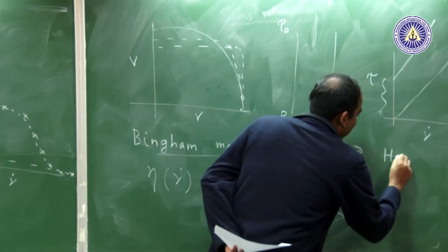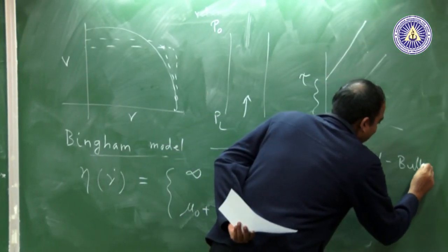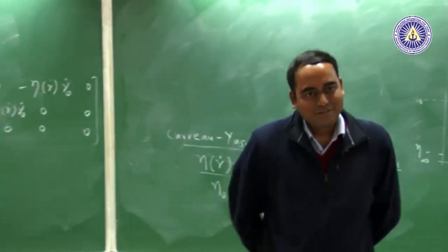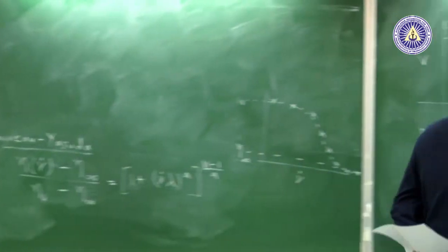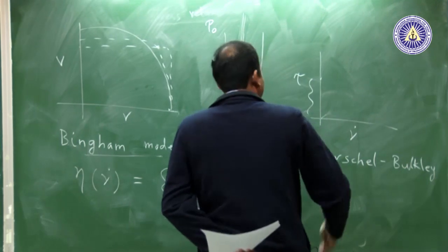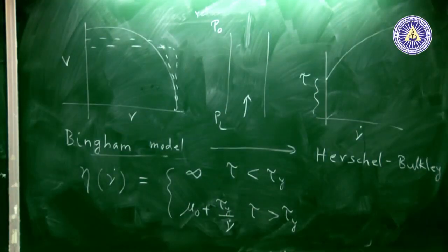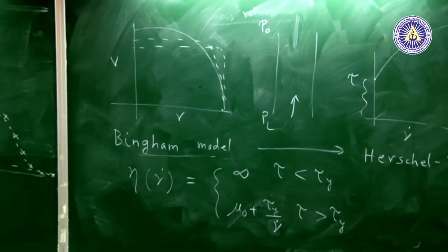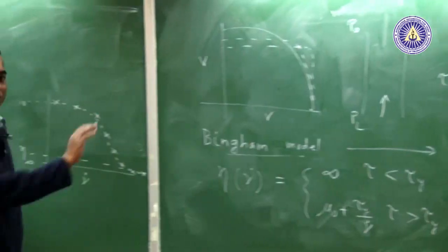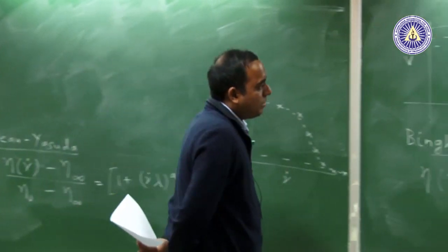So, that is called the Herschel-Bulkley. See, the problem of Herschel-Bulkley is because of the power law nature. In a Herschel-Bulkley fluid, you are exactly right, there would be a yield stress, but then it can be curved. Now, the problem of this is the computations are a little bit more difficult, but for some simple flow problems you can still do it,